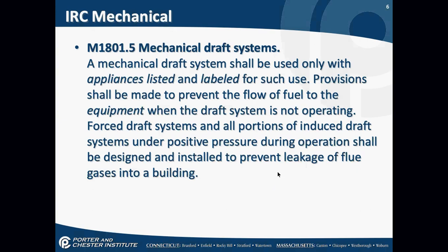Okay. A mechanical draft system, in other words power venters and draft boosters, can only be used with appliances labeled and listed for such use. We have to put in safety switches to prevent the flow of fuel to the equipment if the system does not run. So if I have a power venter or a draft booster on the chimney, I have to have some cutouts available, so if the draft system doesn't run, the furnace doesn't keep running.